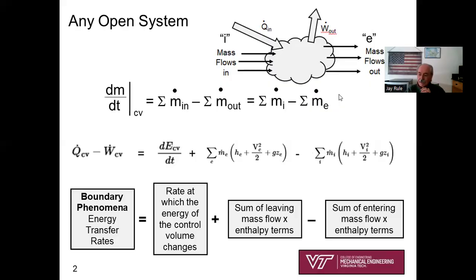Minus another big block of terms, the sum of the m dot n with those related enthalpy terms there. Okay, and let's see, how did H come into play all of a sudden in chapter 4? It had to do with flow work. So we went through it, we remembered it, but we just got exposed to that. That didn't come into problem solving other than remembering that when you have open system problems, you're dealing with enthalpy, not internal energy.